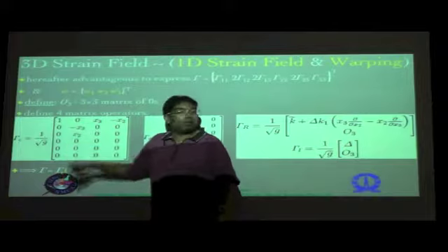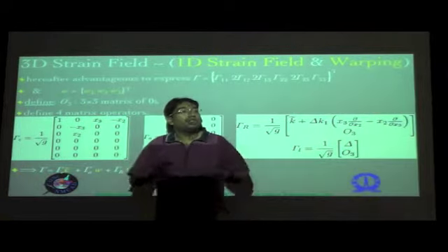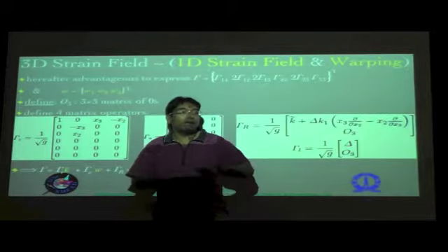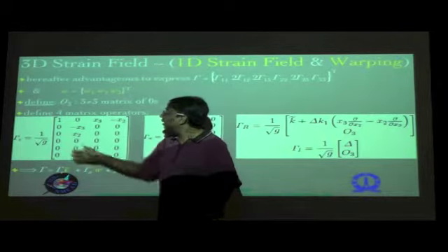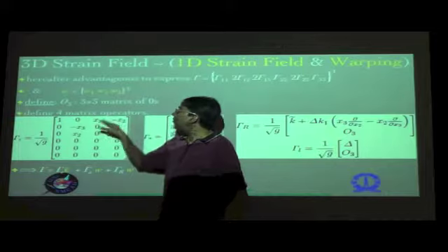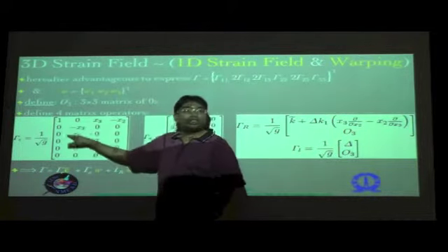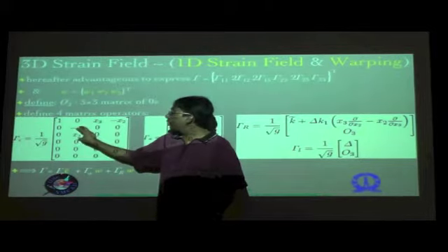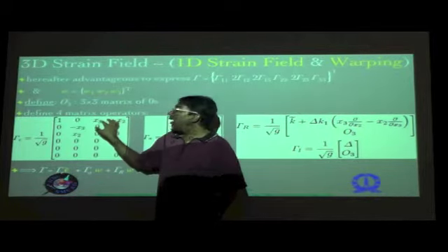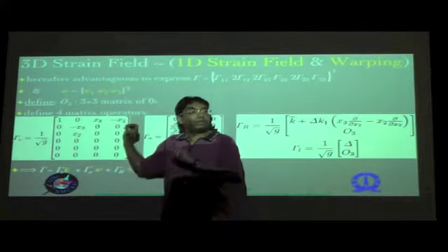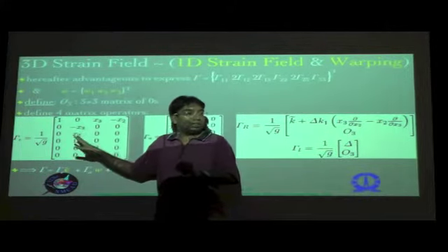So that's basically the shear strain which is caused by twisting the shaft, let us say. So it's just making a generalization of beam theory, column theory, and basically shaft theory. So torsion theory, extension theory, and the bending theory are all combined into a single matrix in the simplest kind of beam formulation that you can have.